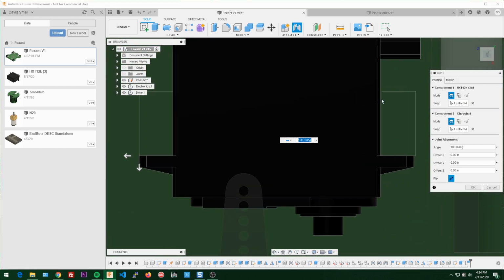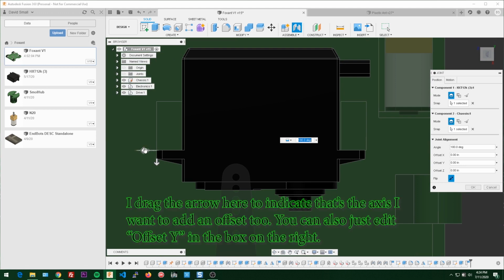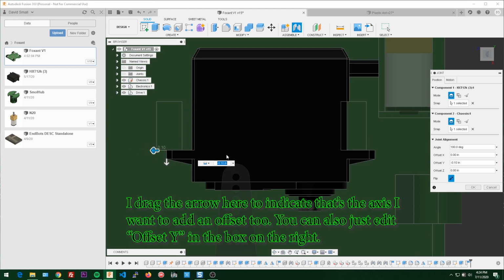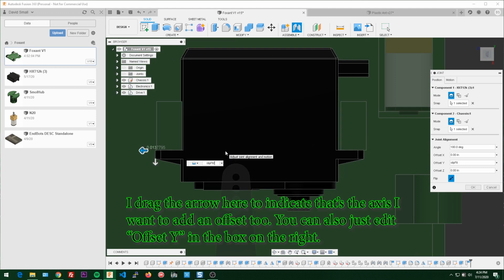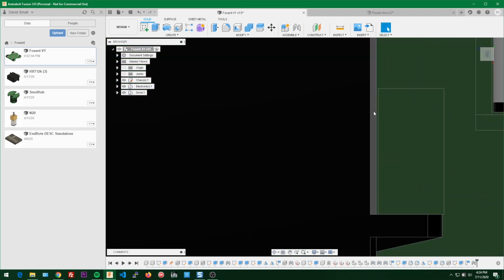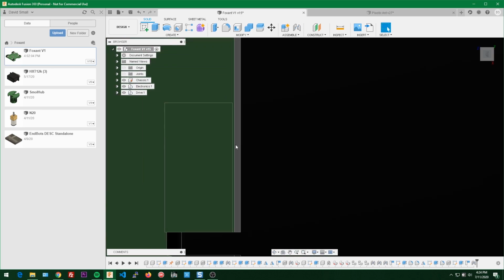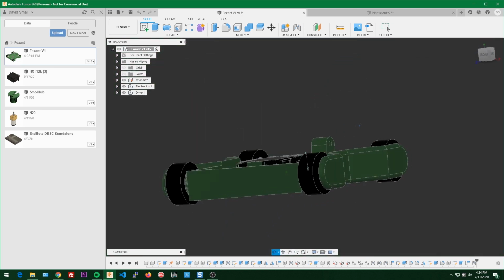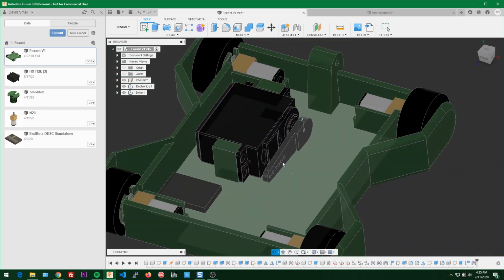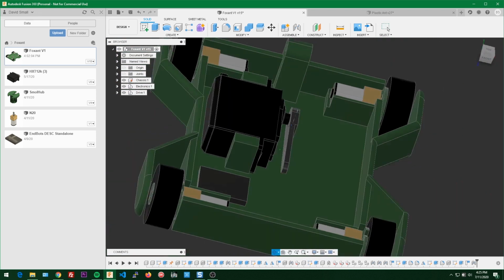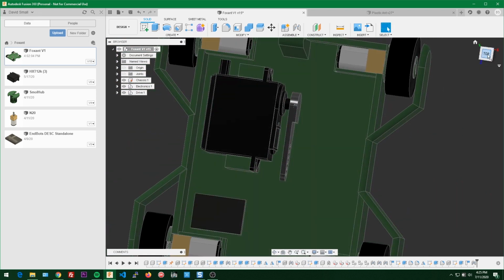And then you can see there's a gap here, so to center this, let's move it by slip fit divided by 2, and that'll center it. Negative slip fit divided by 2. There we go. Just to make sure that it's centered with an equal gap on each side. And there it is. So now we can add holes here for our bolts, but first I kind of want to mess with the positioning here.